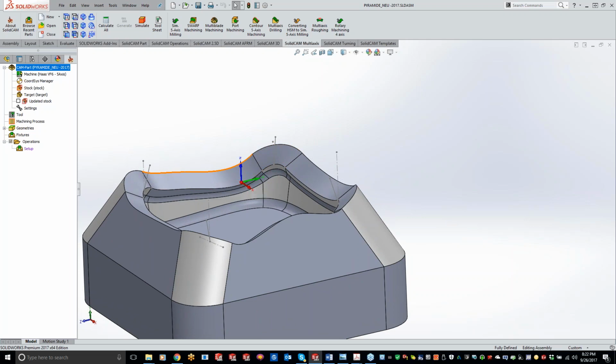That's the only real downfall of using the contour 5-axis, having to draw a couple of those lines in there if there's no geometry there. But the nice thing about it is, for this particular one right here, we don't have a chamfer on this part. You'll see there, I don't have a surface to select right there going all the way around. So this is something I could not do very easily in simultaneous 5-axis because that drive surface is missing. Now, granted, we could draw it in there in SolidWorks and do all that, but it's much easier, simpler just to draw a quick line in there.